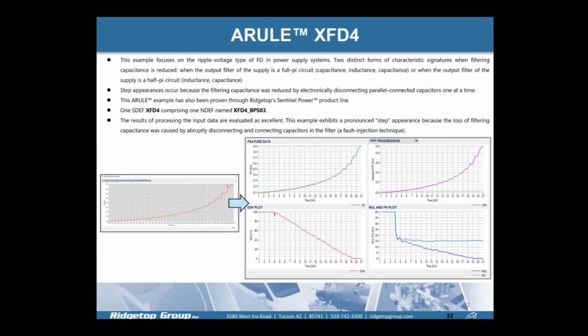Corresponding to that, step appearances occur because the filtering capacitance was reduced electronically by disconnecting parallel connected capacitors one at a time. So this is actually a manual fault injection technique.